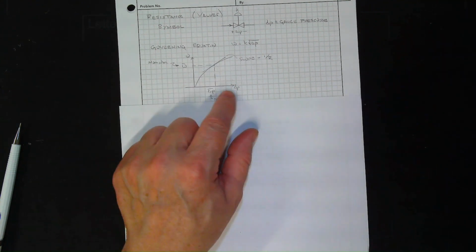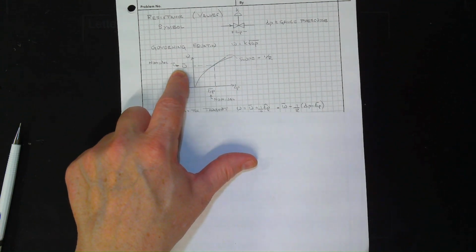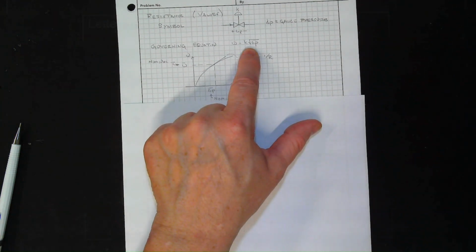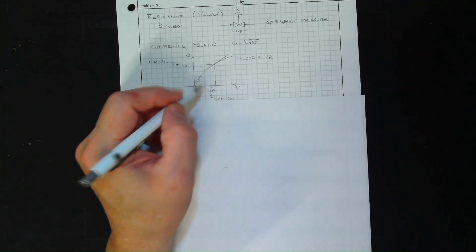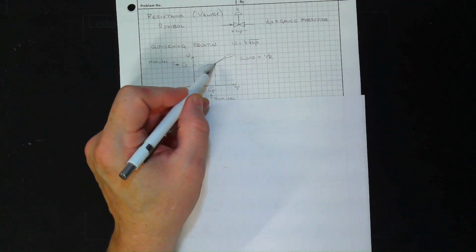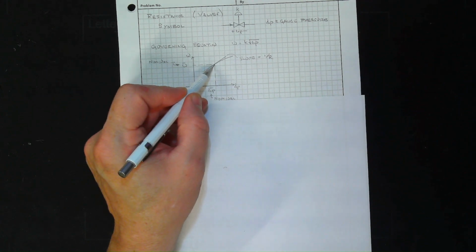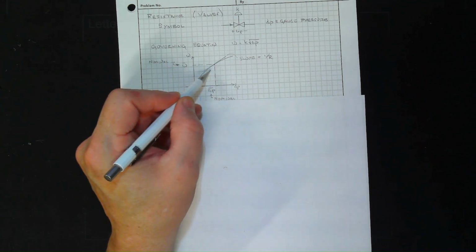All right, so here's what the valve pressure flow curve would look like. As you have the change in pressure, depending on where you are, that would determine the flow rate you get. Now this would be a nonlinear thing to have in a differential equation, so we're going to linearize it. Basically we'll say there's some nominal pressure drop that we're working with, some nominal flow, and we will have perturbations around this point. While this is nonlinear, within a region it'll work fairly well.